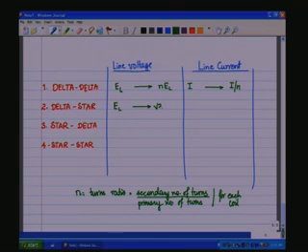So root 3 into N into EL. If we apply a line current I, it becomes I by root 3 as the phase current in the primary side, it becomes I by root 3 by n, the current that is induced on the secondary side, and that itself is the line current on the star side, which is I by root 3 into n.